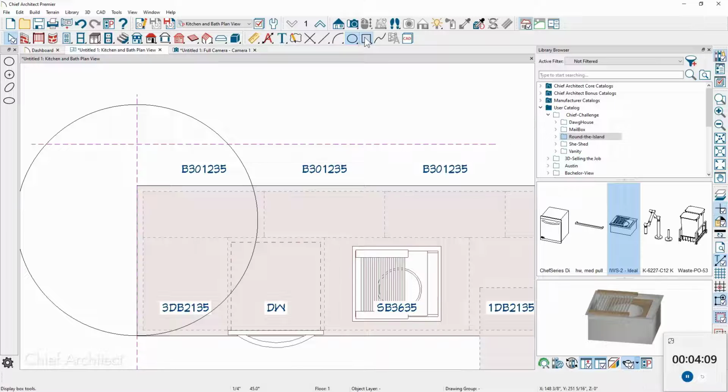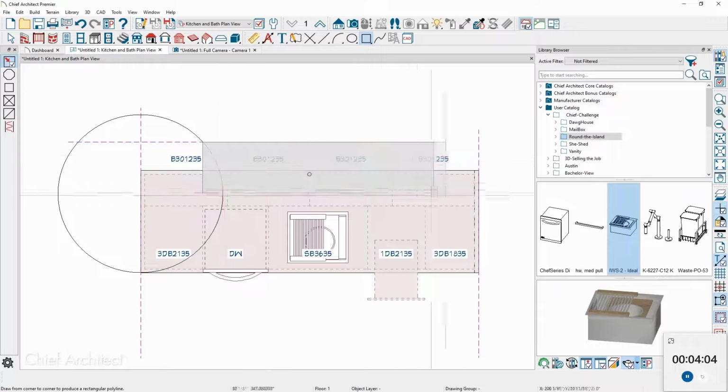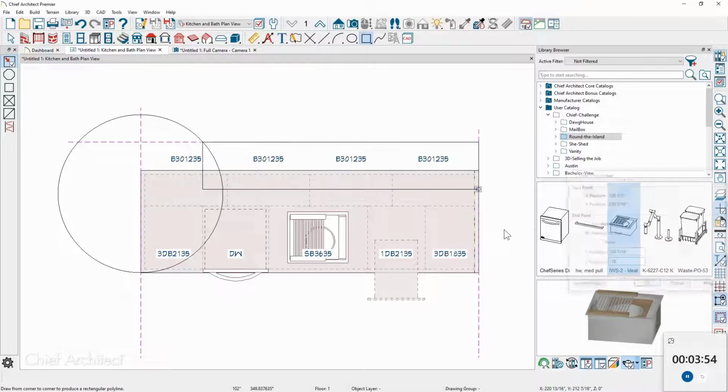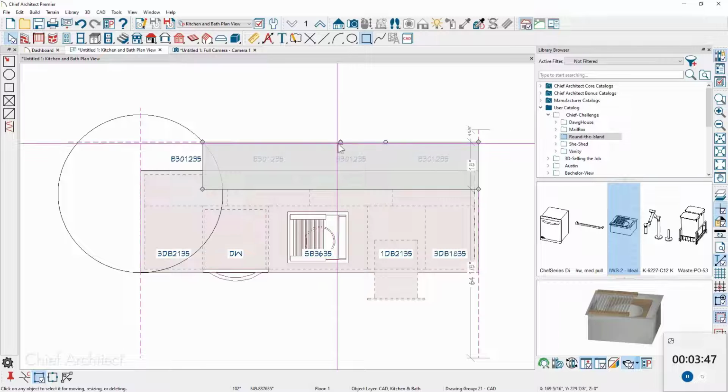I'm going to use the CAD rectangle tool. We'll pick up the snap right in this area. We'll pull it over to the edge of the waterfall. Before I release, I'm going to press the tab key, uncheck polar, and the dimension that I want for that countertop is 18 inches. So now that I've got the shape for this river swoop, I'm going to use the break command. We'll pick up the midpoint,